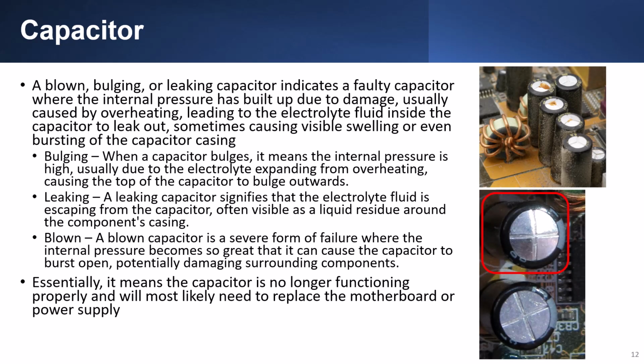A blown, bulging, or leaking capacitor indicates a faulty capacitor where the internal pressure has built up due to damage, usually caused by overheating, leading to the electrolyte fluid inside the capacitor to leak out, sometimes causing visible swelling or even bursting of the capacitor casing.